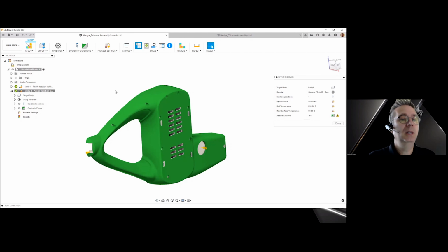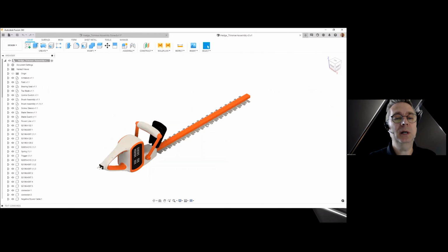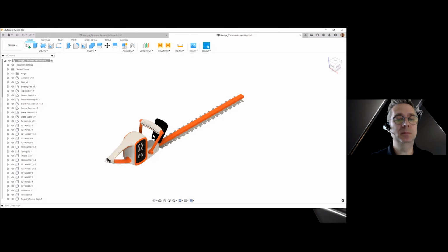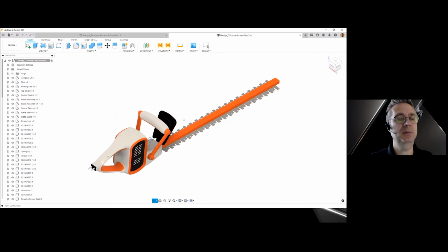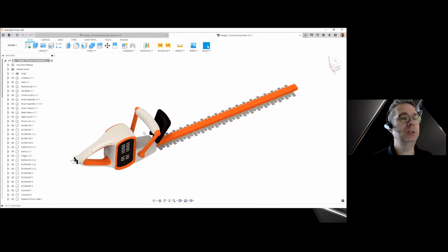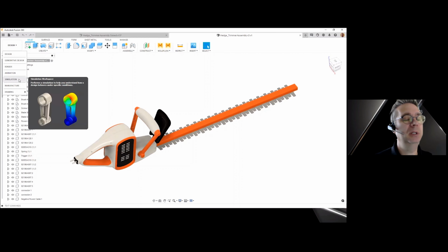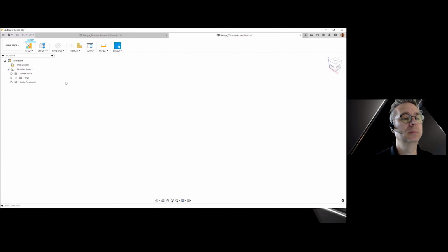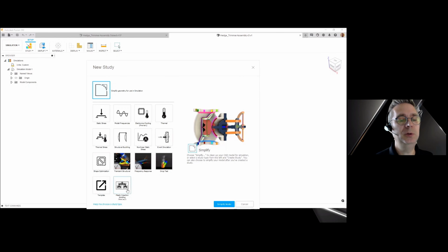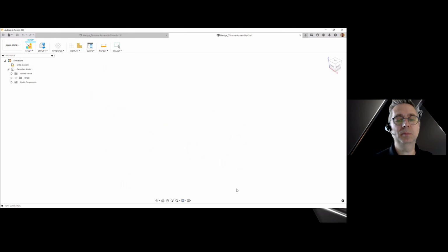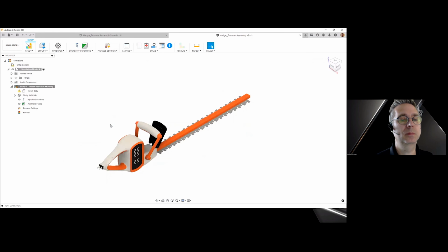Sounds good, Anno. Excellent. So let's see. I read this file in directly just a minute ago. Let's take a look. If I want to look at the new injection molding in Fusion, we're going to come over here to Design and change over to our Simulation workspace. Here it shows Preview at the very bottom there for our plastic injection molding simulation. It's going to read in.